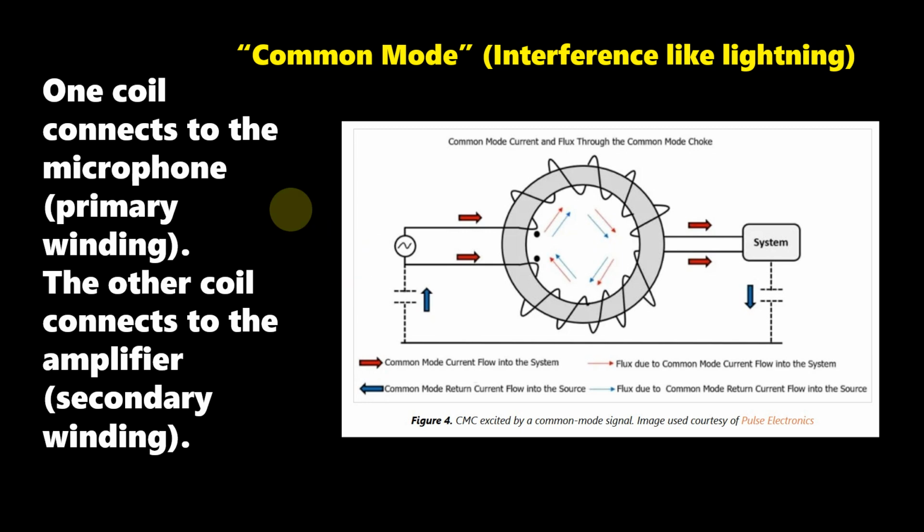Oops, okay. Now in common mode interference, what happens is both lines get the same voltage or push, let's say from a lightning bolt. And what happens is they don't create a magnetic field that is picked up by this method, because again, this really works with alternating voltages, essentially oscillating voltages, from a microphone or something like that.